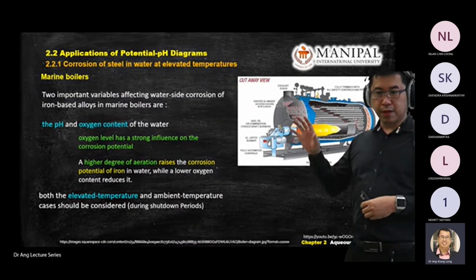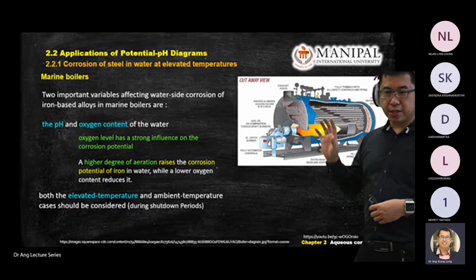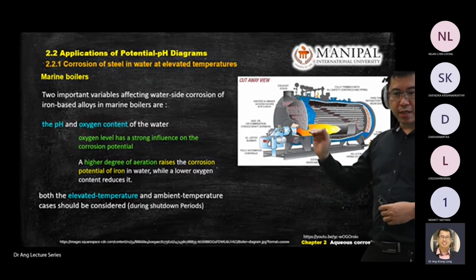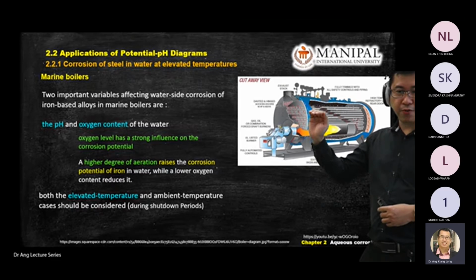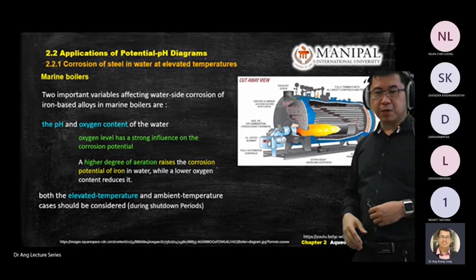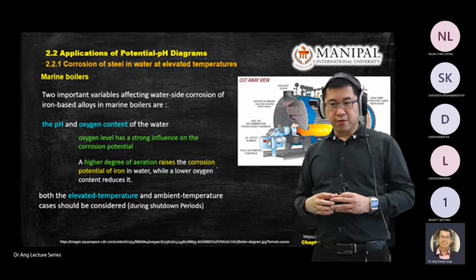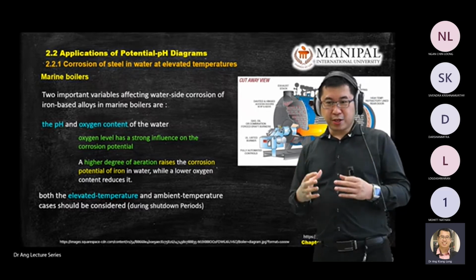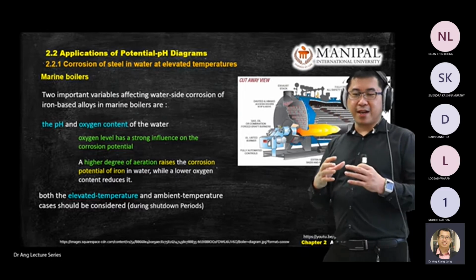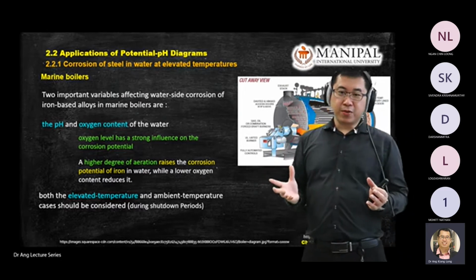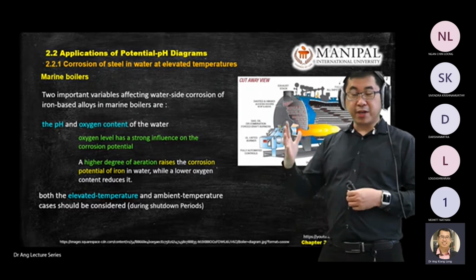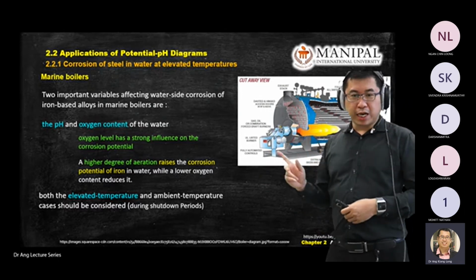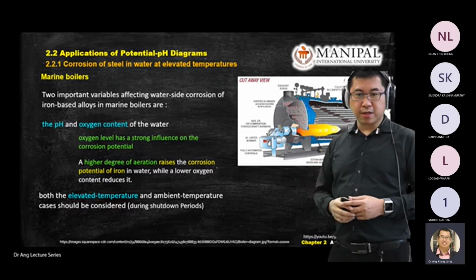A specialized engineer will be stationed for that specific boiler to monitor the rate of increase of temperature and also the rate of dropping of the temperature. Because metal, when it increases very fast and drops very fast to a low temperature, will change phases. As you learned in materials, metal will become brittle if you have a very drastic drop of temperature. So be careful when you go to work later, especially if you come across a boiler operation.